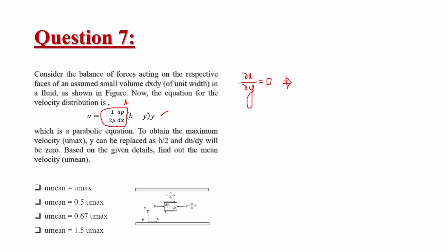So we know that Reynolds number is equal to rho v d by mu, which is nothing but the ratio of inertial forces by viscous forces. It is given that for a low value of Reynolds number, clearly the viscous forces will be dominating or will be larger in comparison to the inertial forces.